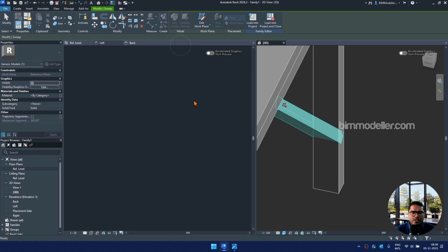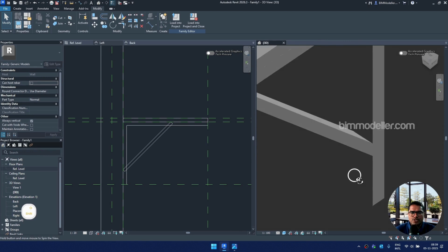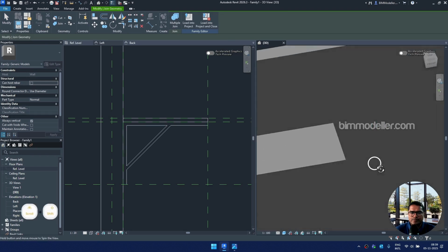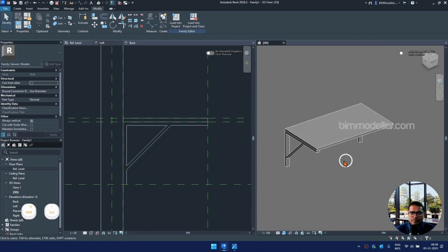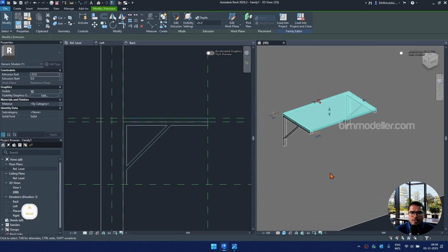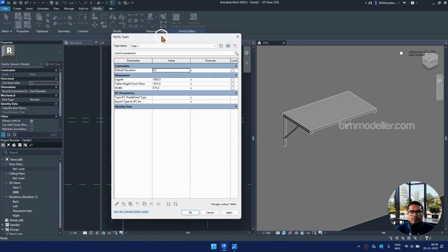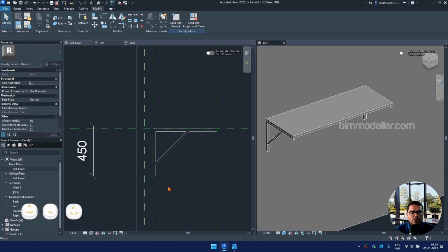And we can go ahead and join these two geometries. So this is how you'll be able to create the parametric families for the objects that we have, the table. So it will act as a parametric on the length side. The height side we did not lock, as it is not going to be parametric on the height side. To constrain that, we may have to configure these heights as well.